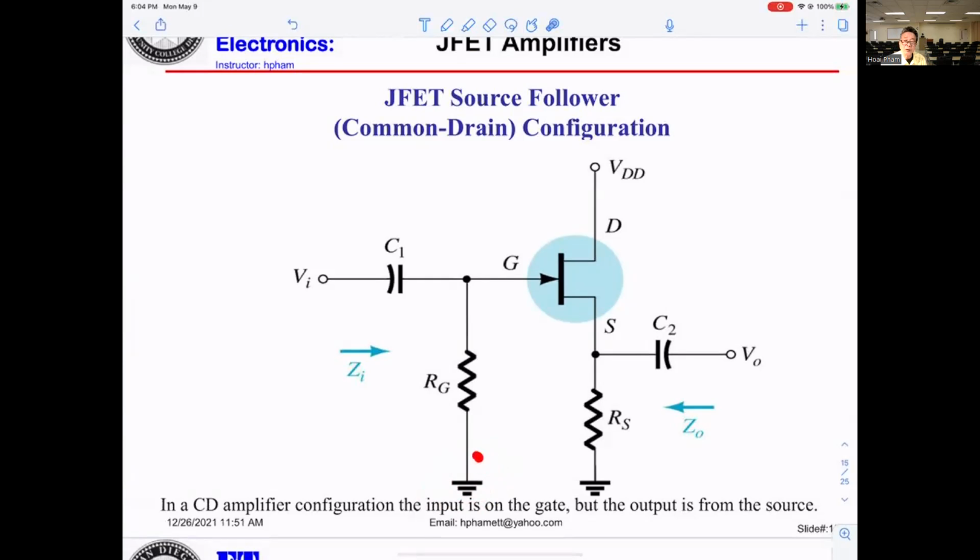That will be self bias. And without the graphic, if you want to do calculation, they have to give you some value. Okay, so you can calculate the DC bias. And if I'm looking into the circuitry, input applied to the gate, output now from the source, that is the output. That's what we call common drain.